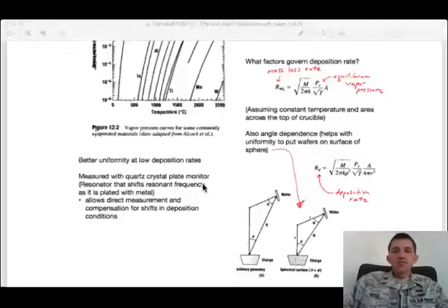You can decrease this problem somewhat by heating the wafer and rotating, right? So if I'm shaded on this side, but I rotate this around, then some of the times I'll be shaded over here, right? So I'm going to get more uniform coverage. And if it's hotter, that increases the probability that an atom comes in and doesn't stick right where it lands, right? It gives it some energy that maybe it can diffuse around a little bit and fill in some of the low spots, right?